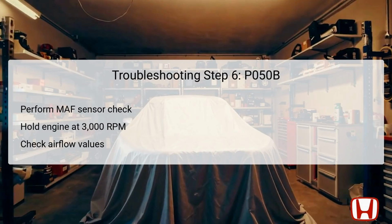parameters using the HDS. Verify that the recorded airflow values fall within the threshold of 4.1 to 5.7 grams per second. If the current conditions do not meet the threshold, it indicates a potential issue with the MAF IAT sensor, necessitating its replacement to ensure proper engine performance.